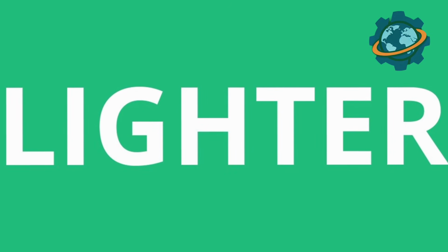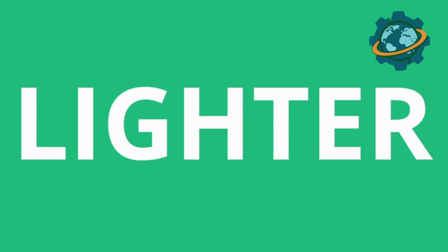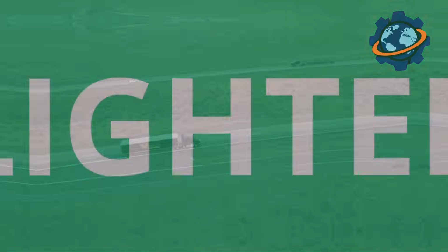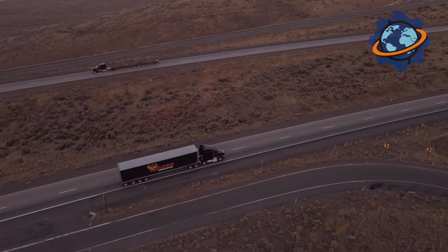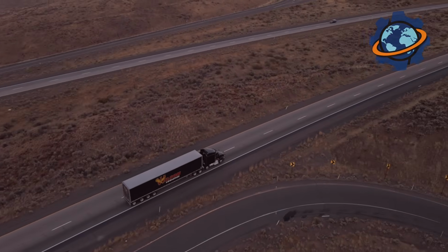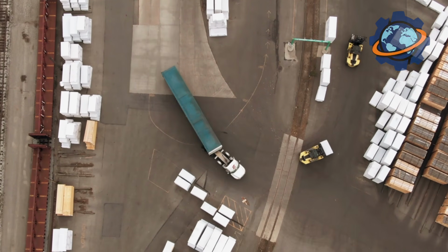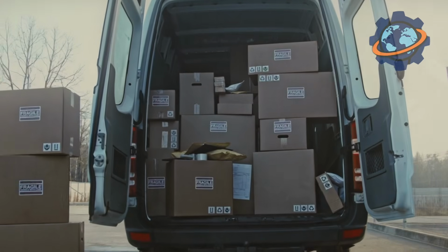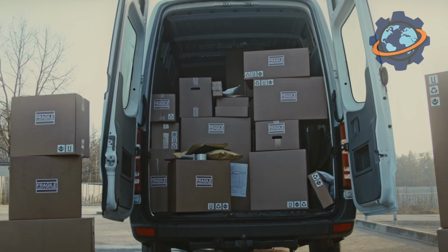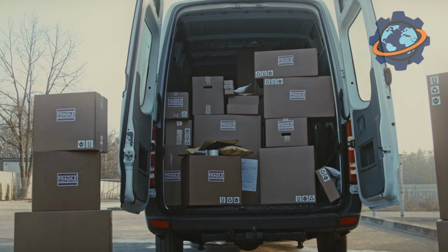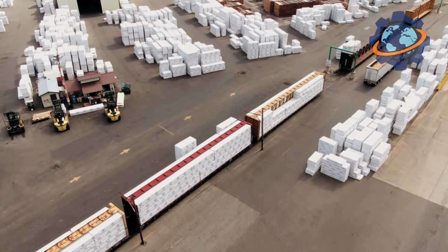The first and most obvious is weight. Fiberglass rebar is about 4 times lighter than steel of the same diameter. Sound boring? Now imagine this in real life. Imagine a truck carrying rebar to a construction site. It can bring 4 times more length of fiberglass rebar in one trip than steel, because it's limited by weight. Or for the same amount, it will take 4 times fewer trips, which saves fuel and time.